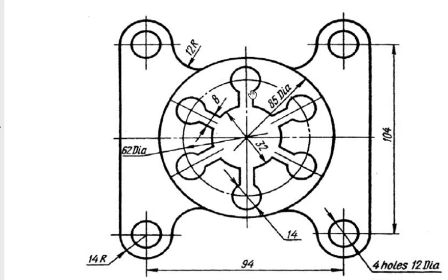After making these 2 lines, we'll make a polar array. That is, we'll make similar sketches to get multiple sketches around some center. Here we'll select this circle and these 2 lines, and choose this as a center, so you'll get a number of similar components. This will act as a parent sketch, and all these become child sketches. After making this, we'll draw 4 different circles and then a larger circle.